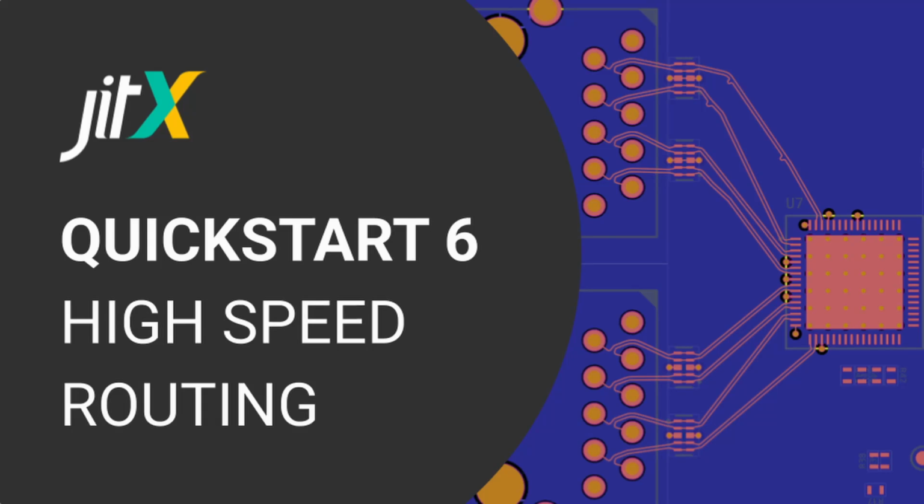In this video, we'll add the gigabit Ethernet interface, using pin assignment to optimize the routability of our design, how to add signal integrity constraints from code, how to create topology constraints for channels that go through multiple components, and how to autoroute high-speed interfaces, including differential pairs.